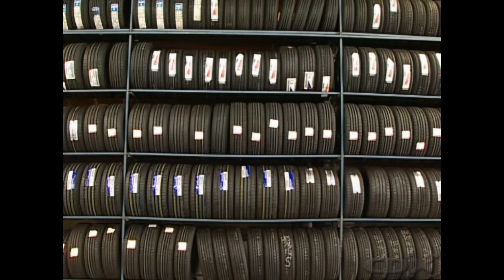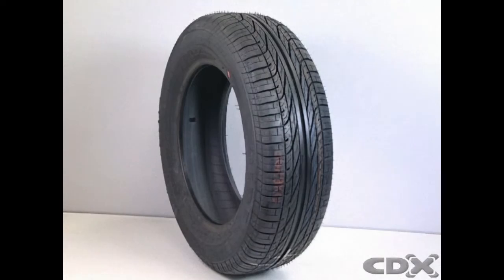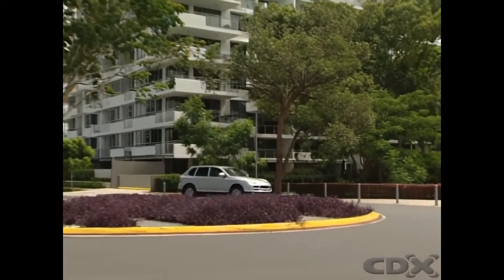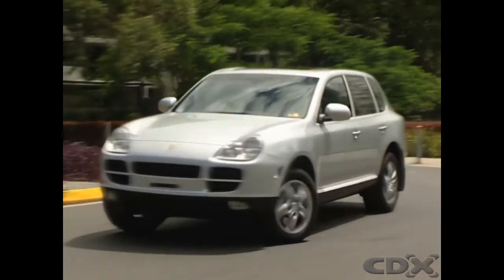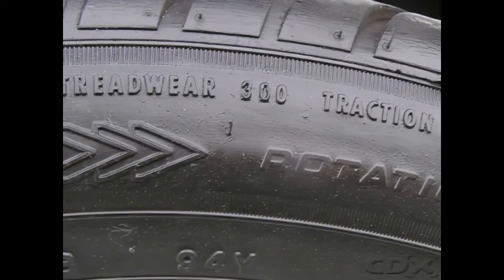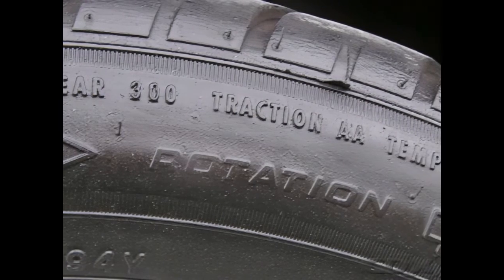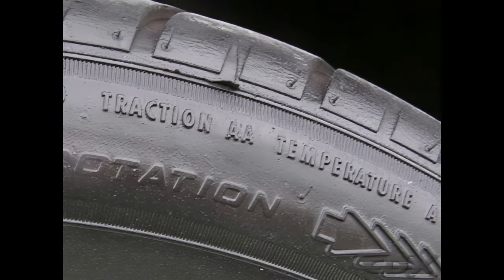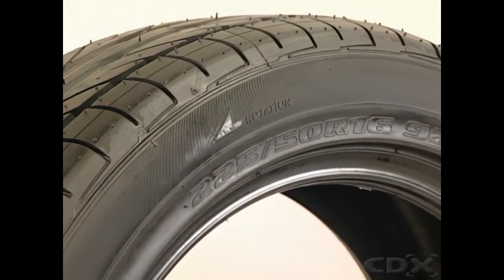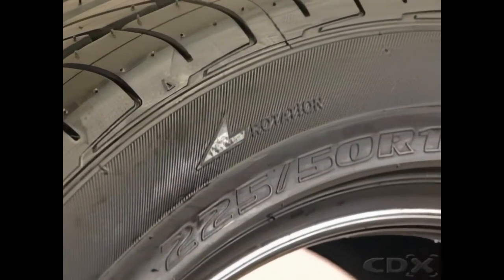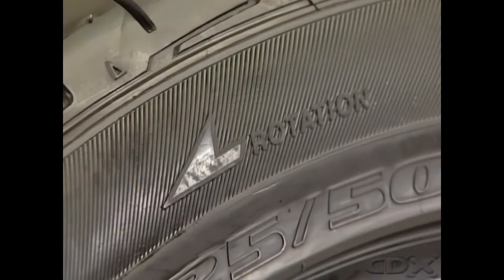Tires generally fall into one of the following categories: directional, non-directional, and symmetric and asymmetric. Directional tread patterns are designed to provide a range of attributes during particular driving conditions. The tire can only be mounted to the wheel so that it revolves in a particular direction to correspond with the tread pattern. An arrow on the tire sidewall indicates the design direction of forward travel.